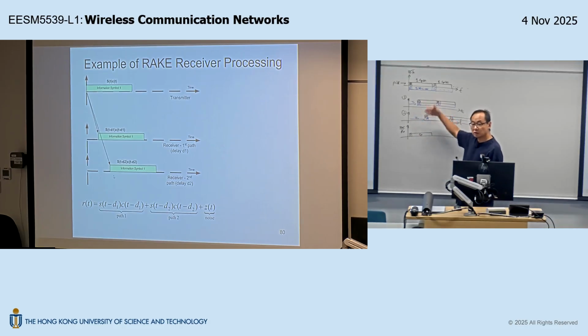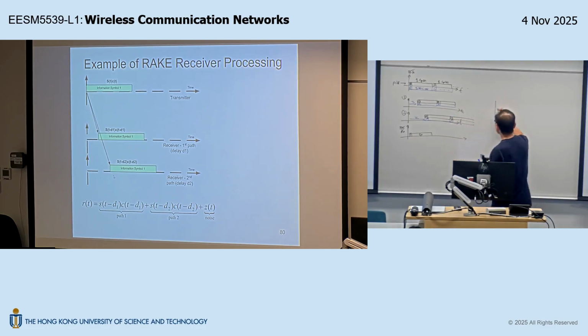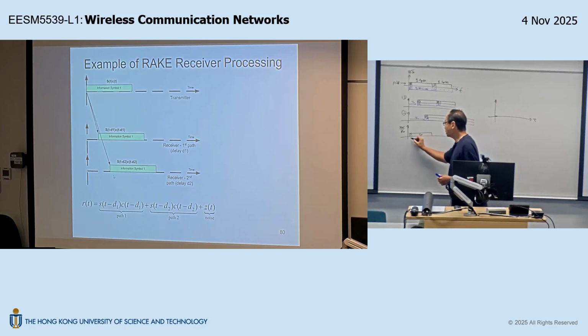This is like despreading the pilot channel with the wrong time. As we talked about last time, if you despread with the wrong time, these broken pieces remain as broken pieces. So at this timing, you get a very low response because you don't have a match, right? So the next timing you try should be this timing. Again, this timing doesn't match, so you keep on having low response, until your local timing becomes this timing.